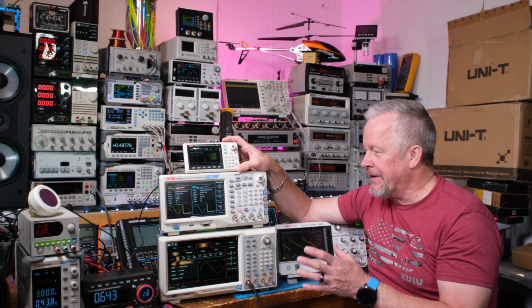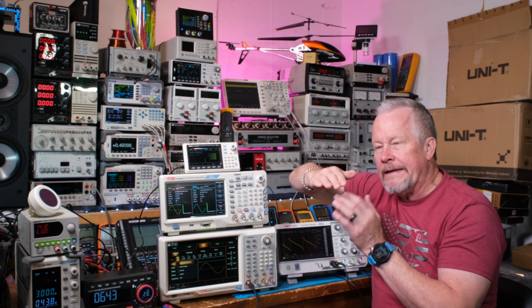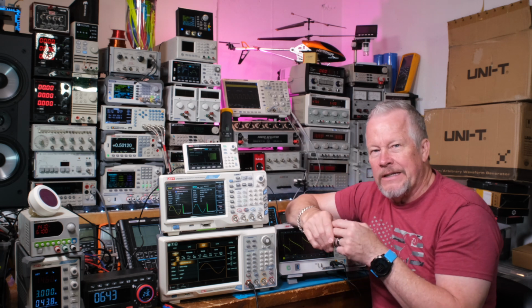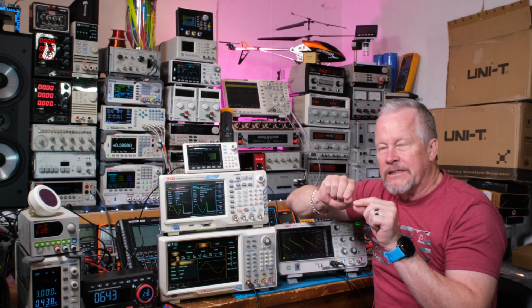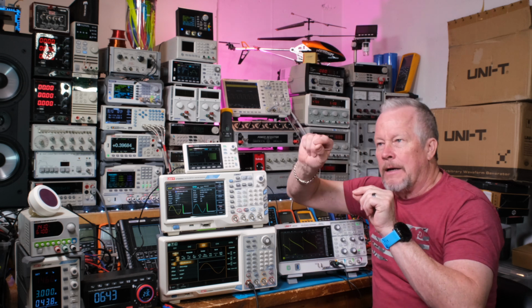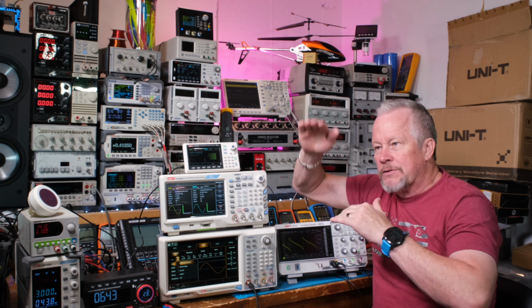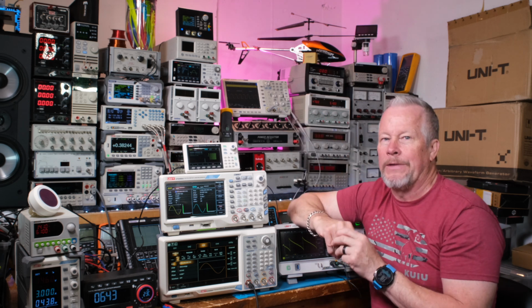All right, so now back to that arbitrary waveform thing. If you're going to build a waveform, you need all that vertical resolution, the horizontal resolution, but then you need memory, because you're going to build all these lines. You can say, okay, go to this point, go out to this time, up to this voltage. If you build some waveform with all these lines of instruction, you need memory to hold that, right?